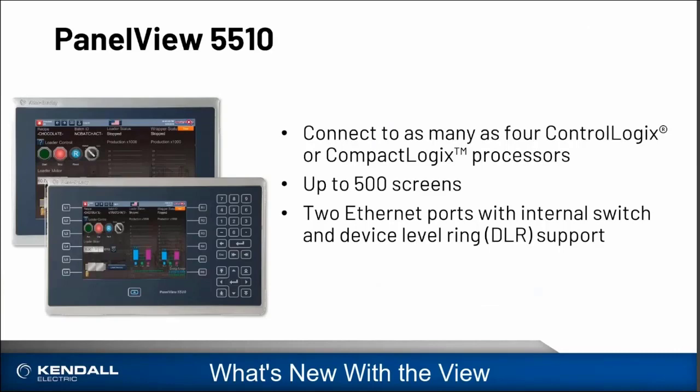Hardware-wise, there are a couple flavors of the PanelView 5000, the 5510 and the 5310. Let's start off with the PanelView 5510. With this panel, you can connect up to 4 processors and support up to 500 screens. It has a dual-core processor and comes standard with 2 Ethernet ports. They come in a wide array of sizes from 7 inches to 19 inches, with a few wide options available as well. All of the 5510 options come standard with the physical navigation button and can be optioned with physical keypad buttons.